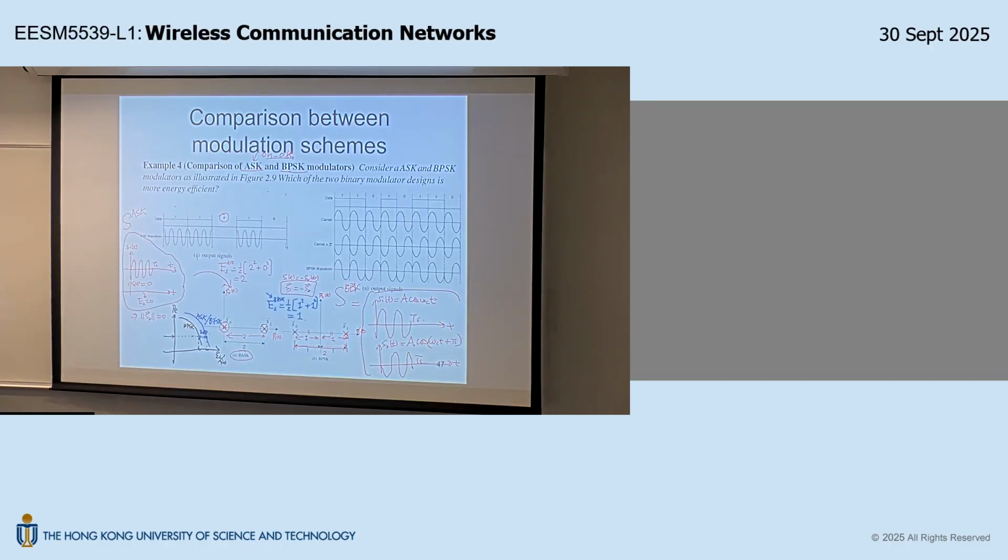And now looking at this, you see the symmetry here, right? Because now when you have 4 points, you have 4 noise clouds, right? So visualize an imaginary virtual noise cloud overlaid on top of each of these points. So you can see the error probability depends on the overlapping area. And the overlapping area now depends on the bottleneck, right? So I argue, on a 2-dimensional space, this is the best way to put the 4 points. Because